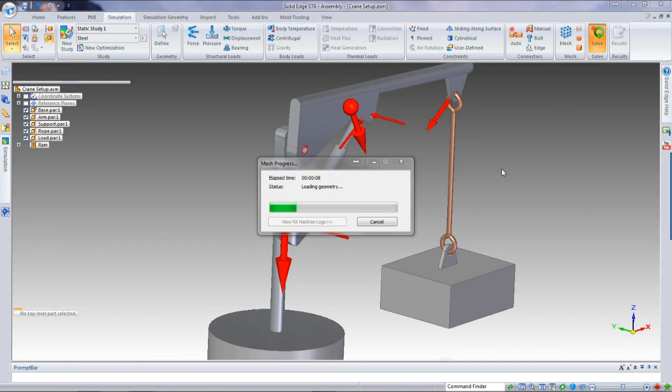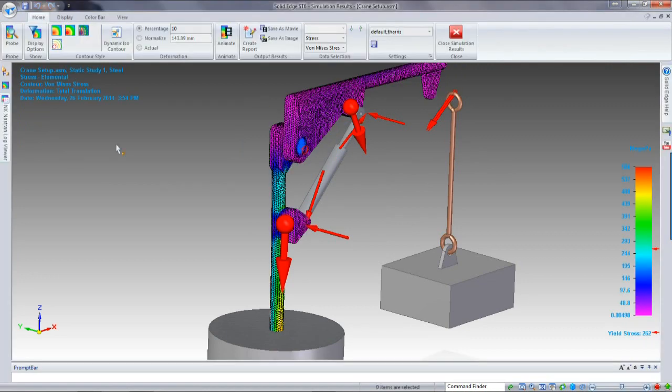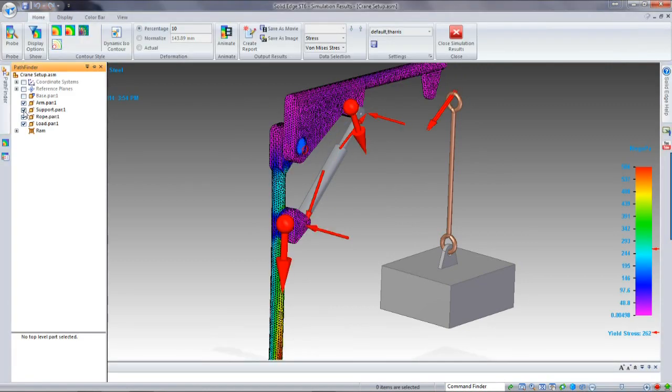If needed, it will remesh, and then it will apply the loads from our Dynamic Design and Motion, which are dynamic loads, into this static simulation and give us the results of how stressed this model will be under that dynamic load case. And we'll see the results in just a second or so. This is a particularly powerful tool because it extends the simulation capability by working out the dynamic load cases for you.